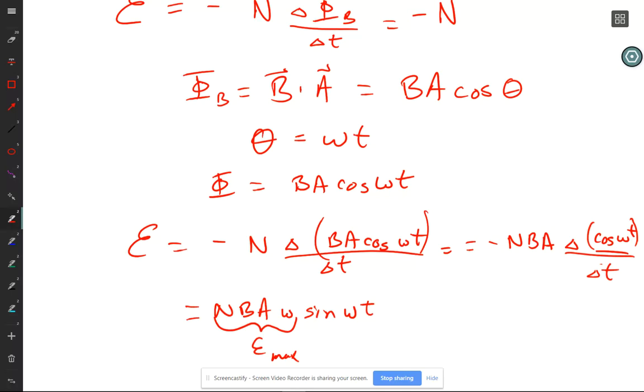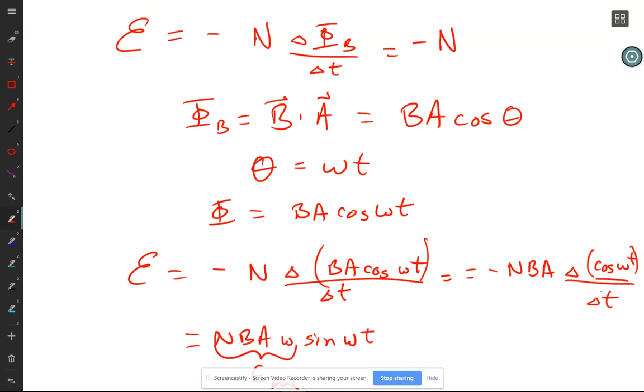If you change the magnetic flux more rapidly, just look back at that first equation at the top of the screen. Change in magnetic flux over change in time. If the change is rapid, what's that doing to the voltage? It's increasing it. So you can increase the voltage quite a bit by having magnetic fields change back and forth much more rapidly. So one rotation, you have like 20 changes from north to south to north to south.